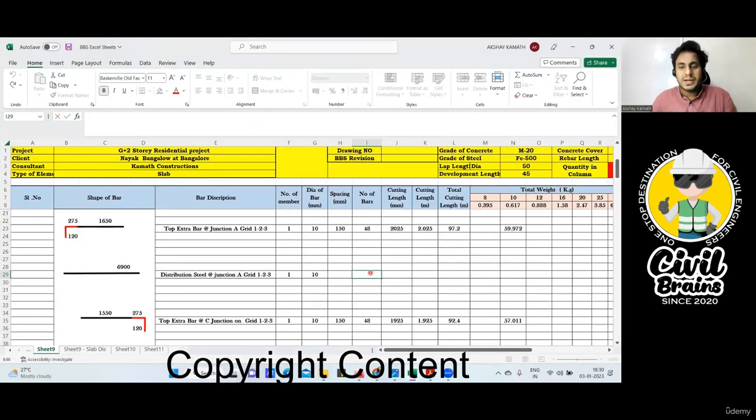So in the number of bar, what I'll do is, I'll click on this. I'll open the bracket. I'll say 1650 divide by spacing. So spacing, I need to click on this. But wait, spacing is 150. Now I'll write 150. And now I'll write plus, open the bracket. Say 1650 is a clear span, divided by spacing. I'll close the bracket. Then plus 1.